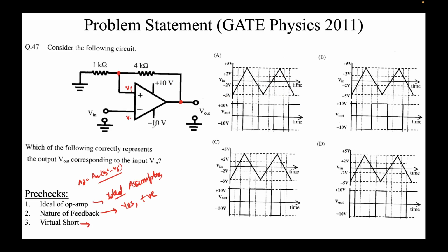Let's say there's a resistor Rin over here, and a current I plus is flowing in. Whatever I plus is flowing in should flow out here also. So I can write Ohm's law across this resistor: I plus times Rin is equal to V plus minus V minus.